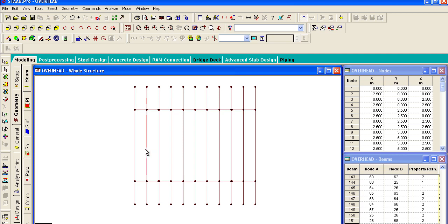So we are just going to apply a template on this. Alternatively, we can avoid meshing, then transfer the loads from the plates as uniformly distributed load to the secondary beams. That's also an alternative that can be thought of.